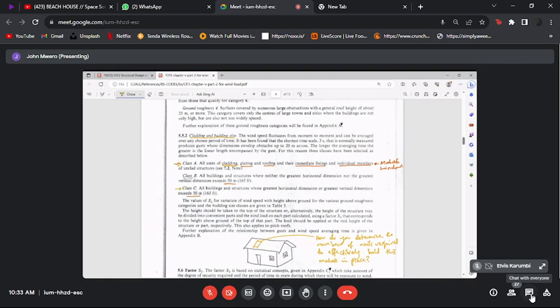I hope what I'm saying makes sense. Now, I'm coming back to the cladding units, because this is something that you find a lot of engineers don't bother to check. Okay, so rule of thumb, but you find the extreme cases, like when you have to design those very luxury homes. So the glass panel that will go into that window would be a structural element able to resist the pressure that you have calculated. So you check it in bending and specify adequate thickness and maybe adequate lamination for this glass to be able to resist the pressure that you will have calculated from whatever wind speed you'll have derived.